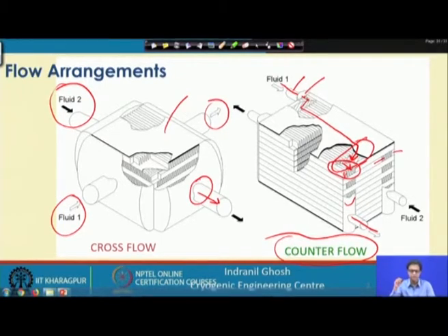So, how do we fabricate this kind of exchangers? We will briefly discuss those techniques, and as you can understand, we have the primary heat transfer surface area, and with that we have to connect the fins, and we need a good thermal contact, otherwise they are going to introduce some kind of resistances which will ultimately degrade the thermal performance of the heat exchanger.